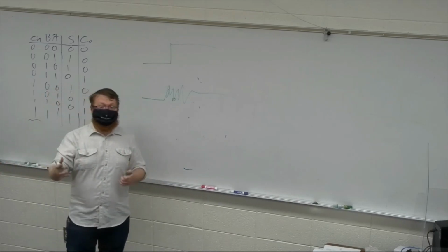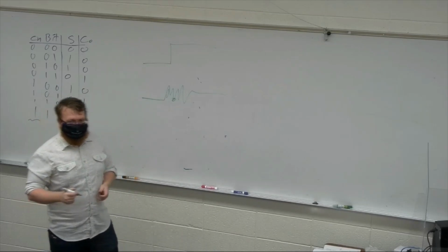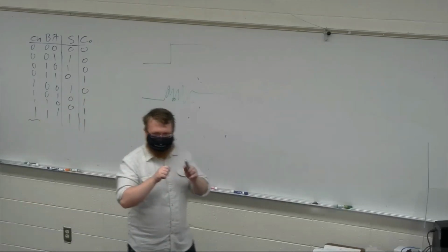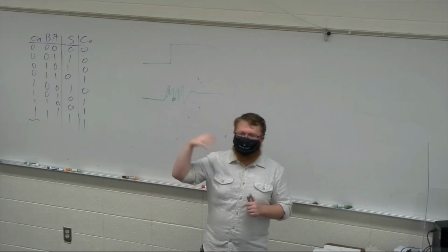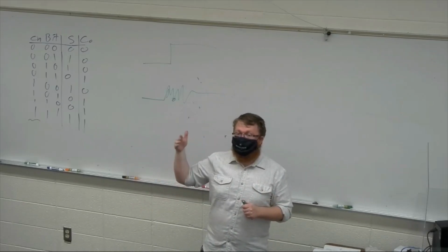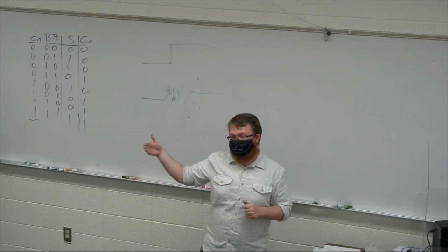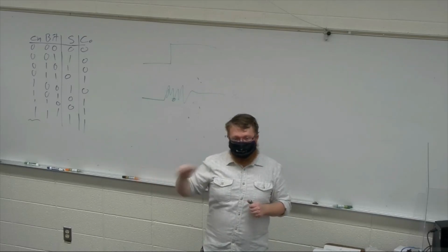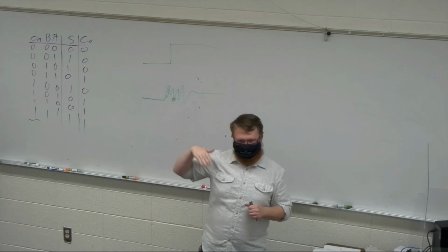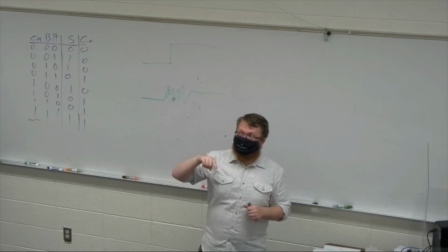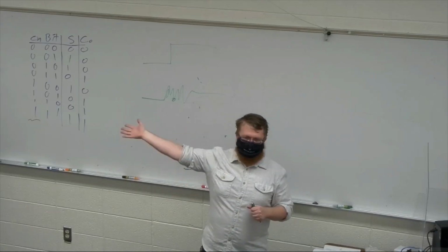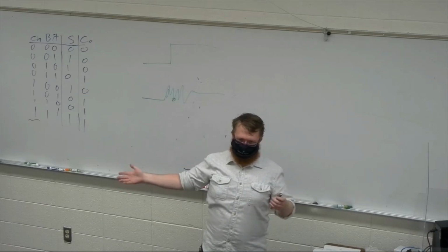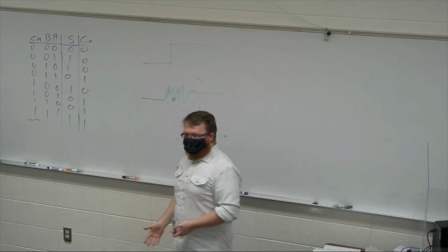You guys may actually encounter this on your board when you're doing the little switches, right, to control the most significant bits of your DAC. You throw a switch, and if you have a process that's just watching for a change in the switches, you throw that switch, it's going to go change, change, change, change, right? And depending how the rest of that state machine is, it might just go change, take it, and then have to go through some other state machine stuff, and then come back, and then you end up with a 0, and it looks wrong.